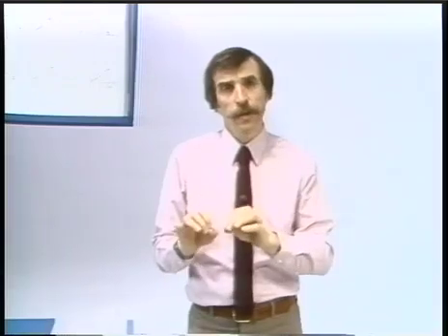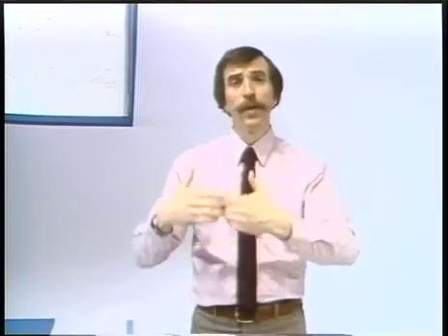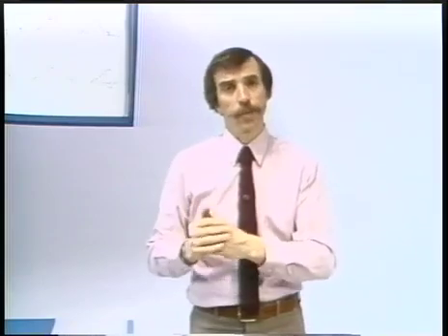In preparation for that, what I would be eager to encourage you to do, using the study guide and in reviewing this lecture, is to begin the next lecture with a careful and thorough understanding of the arguments that I've just gone through, in particular, understanding the process that's involved in going from a continuous time signal through sampling to a discrete time signal, and what that means in the frequency domain in terms of taking the original spectrum, replicating it because of the sampling process, and then rescaling that so that it's periodic with a period of 2 pi.